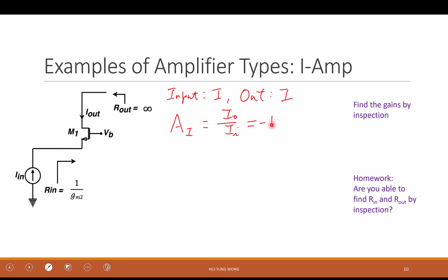Okay. And I'm sure that for those who have never taken any electrical circuit, they can give the answer earlier than you because they clearly see that, hey, I think this one just goes here, it must be 1, this must be equal to this one. But because we know this is a transistor, you thought that there must be something more, right? So we are very hesitant in saying that this is 1. But when there's no channel length modulation, just go through the math, right, and small signal model. You see this must be equal to negative this, right? So the gain is negative 1.